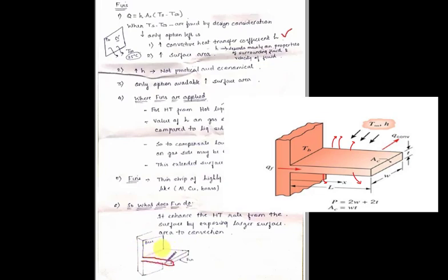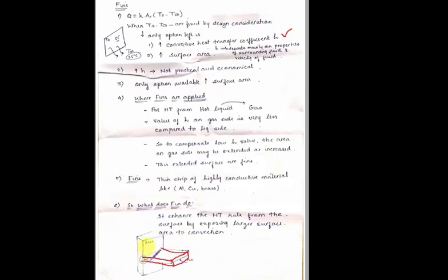This extra portion I have added to this. Now what happens due to this? As the surface area increases, automatically the Q increases. So without installing a fan also I can increase the heat transfer rate, and the option available for this is nothing but these extended surfaces.